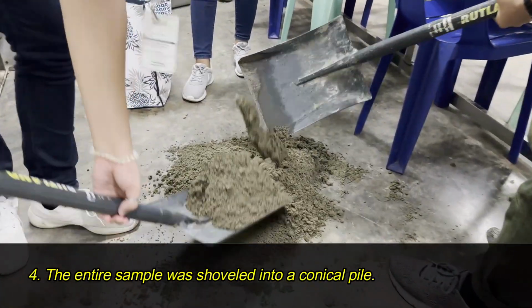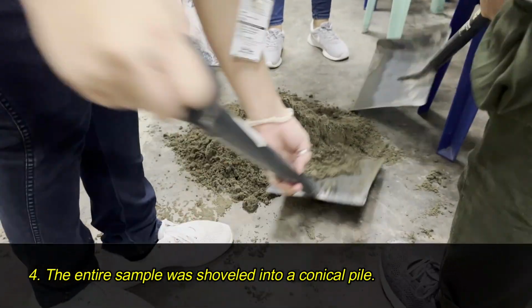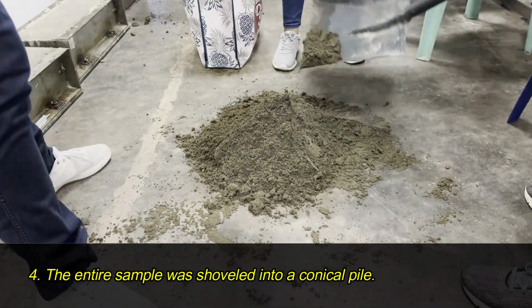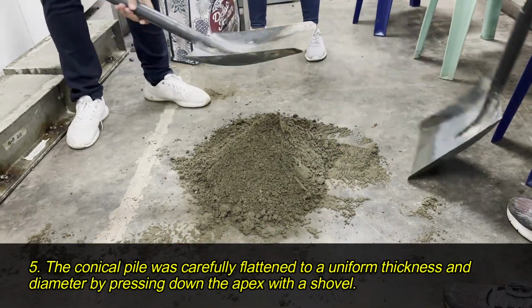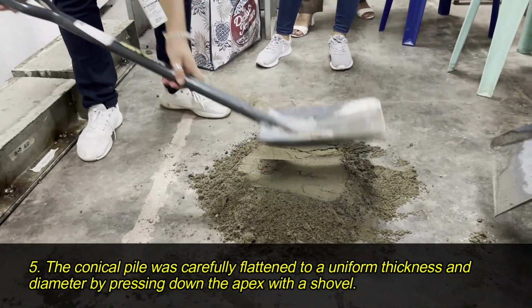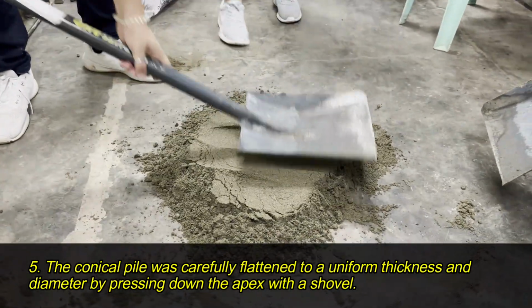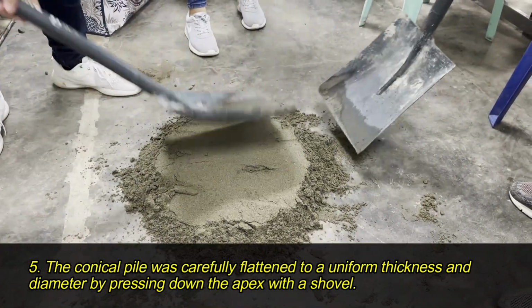Fourth, the entire sample was shoveled into a conical pile. Fifth, the conical pile was carefully flattened to a uniform thickness and diameter by pressing down the apex with a shovel.